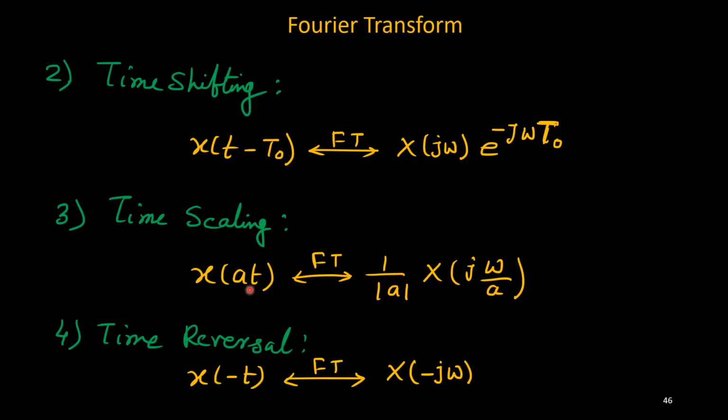Okay, so you can understand that if the signal is expanded in time domain, it means it is changing slowly, thus frequency content will be low. Meaning is that it will be opposite of this one. Again, if the signal is compressed in time domain, it means it is repeating or changing more frequently, meaning frequency is more. Thus, if the signal is expanded in time domain, the spectral is compressed in frequency domain, and vice versa. Okay, that is given by this one.